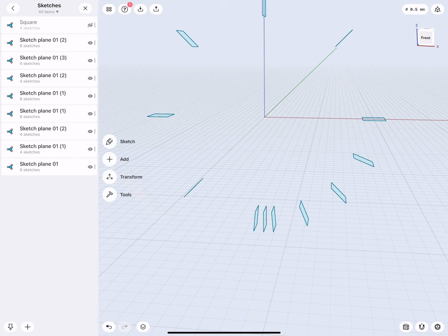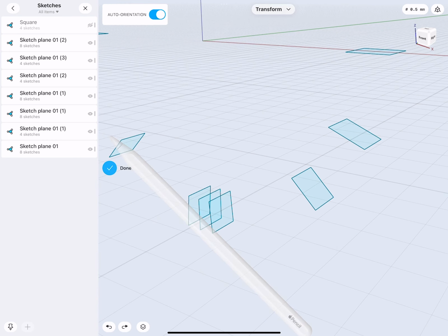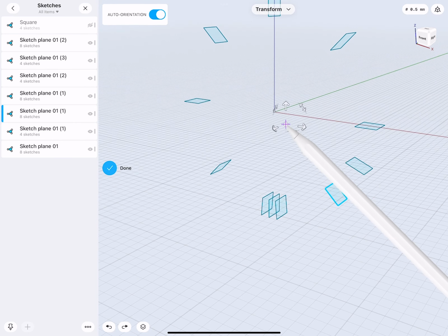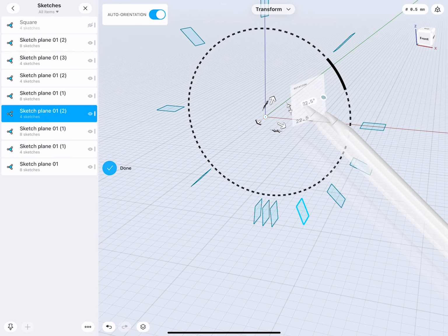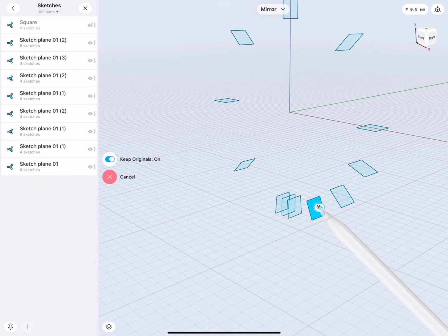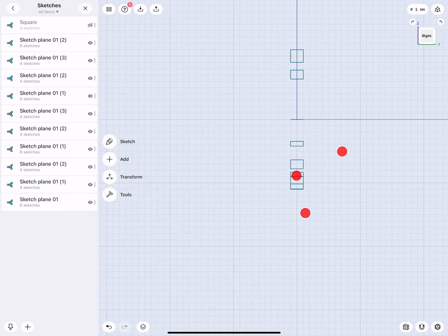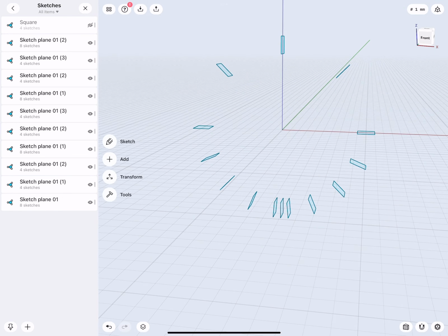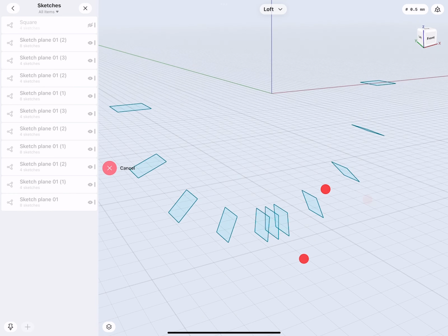If, for example, the math is too much for you, no shame. We can always just work here in sections. Again, you see how easy this actually is because we work with the grid. There we are. And now transform, mirror these two, side view. We make a copy on the other side. There we are. Okay. So let's see when we plot this, how this will look.